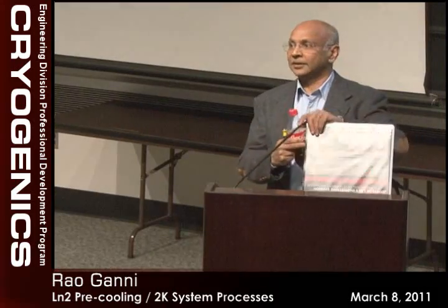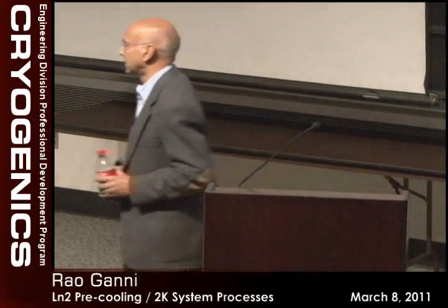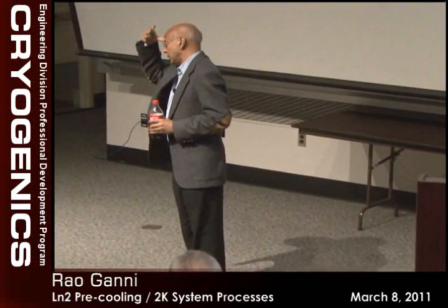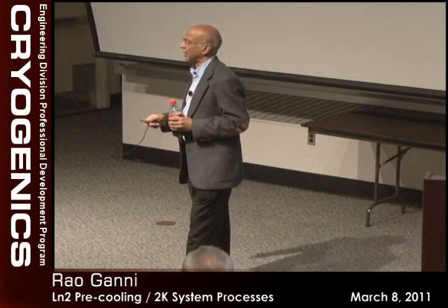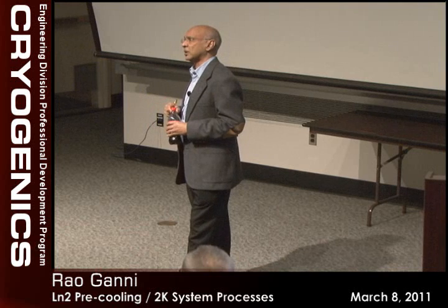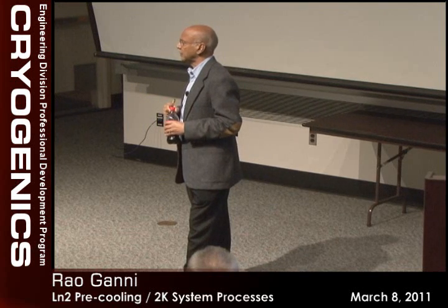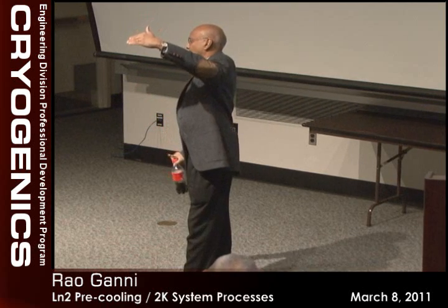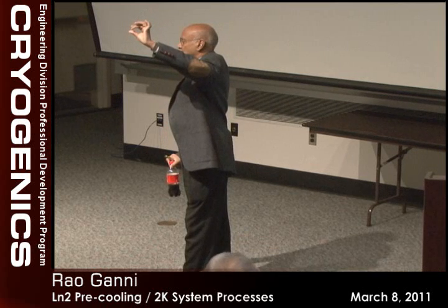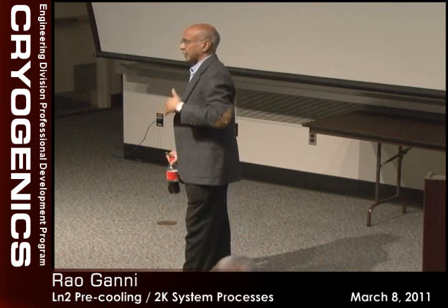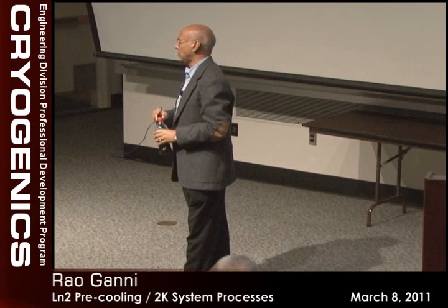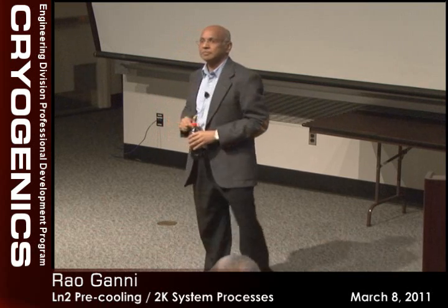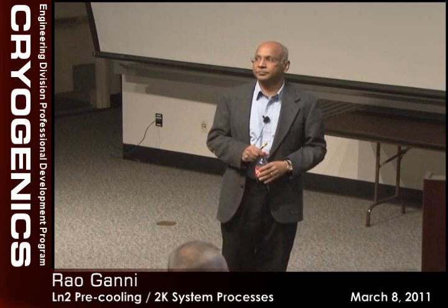One more? How do you maintain your cooling water temperature, the cooling towers? We have cooling towers with fans which vary in speed, and that's where it varies. It varies from winter to summer by I think 10 to 15 degrees, but that doesn't really affect us. We are working from a 300 Kelvin scale to a 2 Kelvin scale, where this change is less than 2 to 3%, and it really does not influence anything except the compressor, so we start the fan, and that's how they balance it. Anybody else?